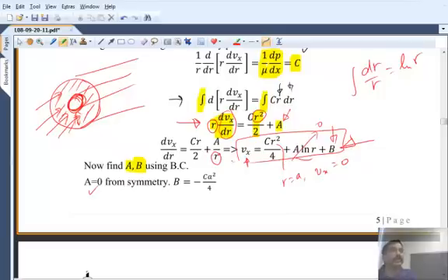One of the boundary conditions will change. From the symmetry condition at the center, because the center doesn't even enter into the problem now, you should put a no-slip condition. When that happens, this term will not be 0. The logarithmic term will be non-zero. We need to find out what A and B are, and then get the flow rate, etc. Okay, does everybody get that?